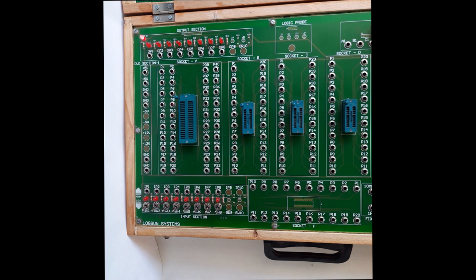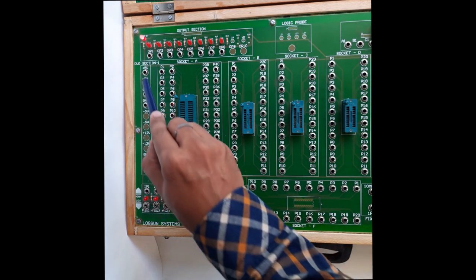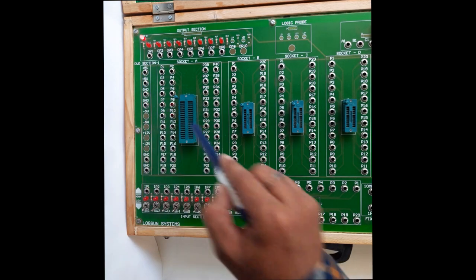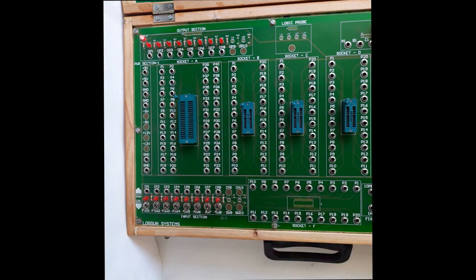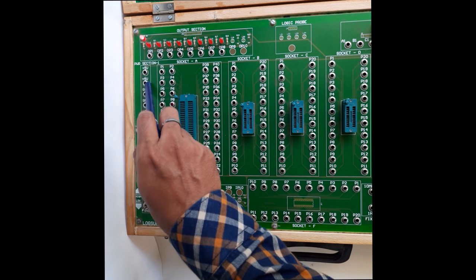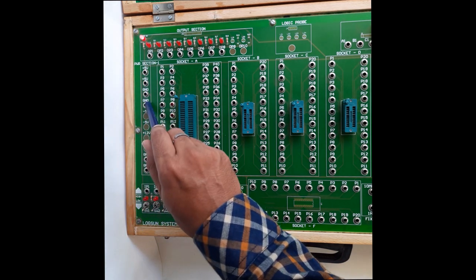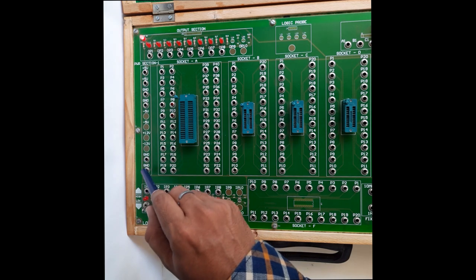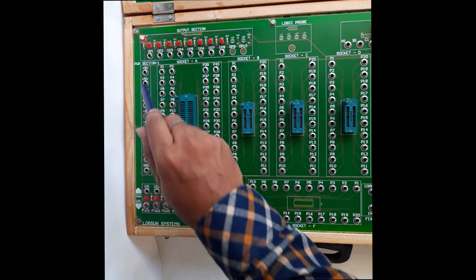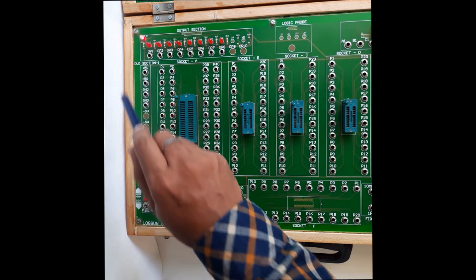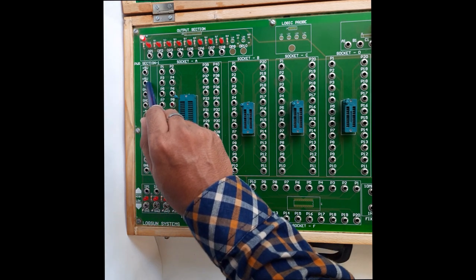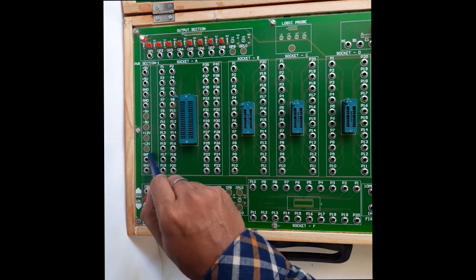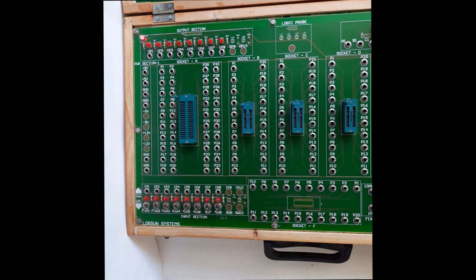But for running any IC we require the VCC and the ground section. For whatever IC we use throughout the practical sessions, the IC requires a VCC power of plus 5 volts. So the plus 5 volts are here. Then the ground section is there. Different ports are given for the ground and the VCC. You can use any port for the ground and the VCC. Here 2 ports are for the VCC and other ports are given for ground. G indicates ground.